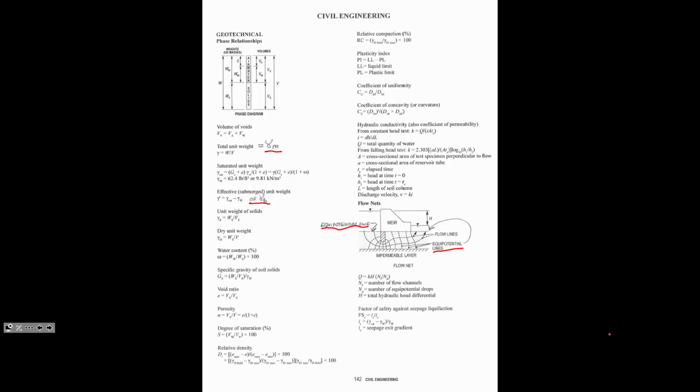Each one of those vertical lines, or each one of the flow lines, as it runs down through here. There's a flow line on the bottom of the weir. There's a flow line along the top of rock, along that impermeable surface. So one of the things they could ask you is, like, how many flow lines are there? How many equal potential drops are there? And I guarantee you there'll be answers where you're not counting either the bottom or the top, or you're not counting the first or the last on the drops. That answer will be there. You absolutely know it'll be there.